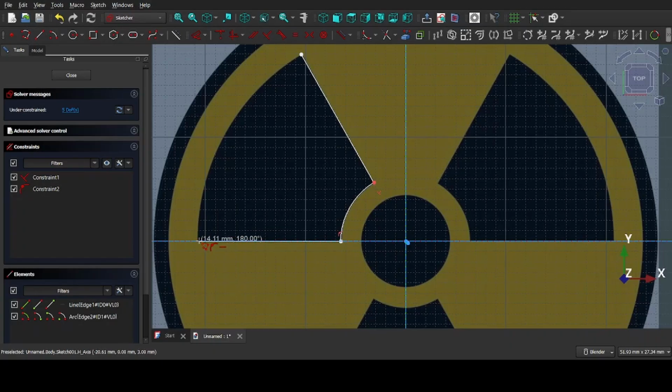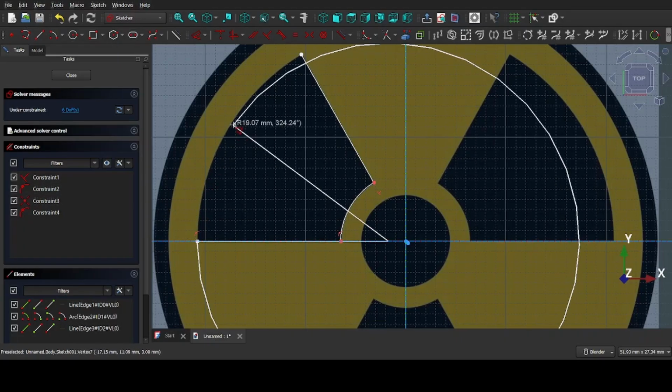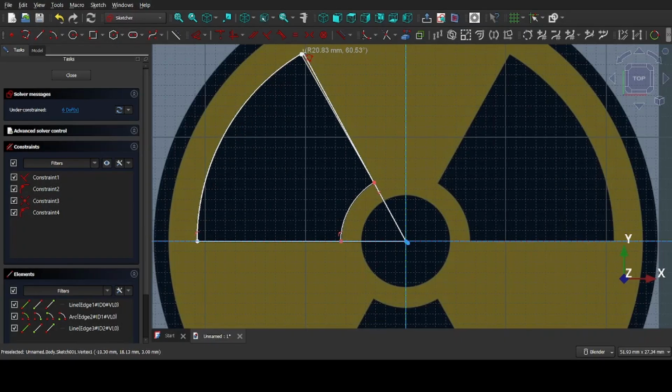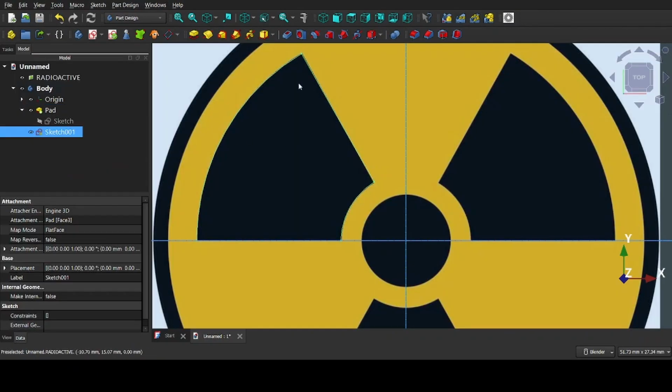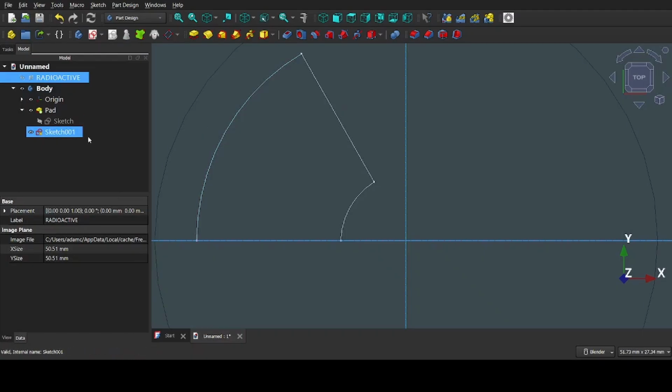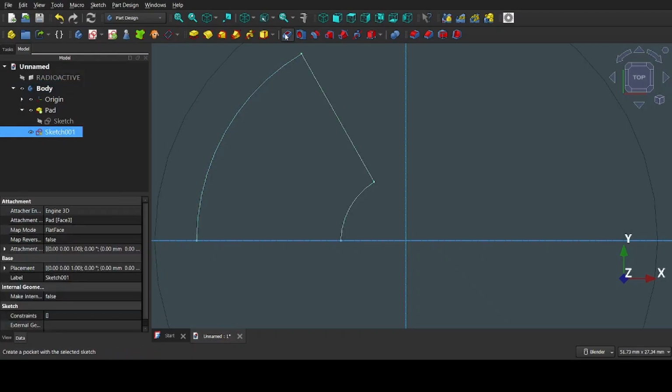And once you get it to the line that is perfectly lining up with this edge, click on a point, and again, click M several times to select the arch again. Complete your drawing, and then right click twice to turn off the tool. Close your sketch, and the sketch is there. Now you can't see it. Turn off the picture, and now you can see your sketch.